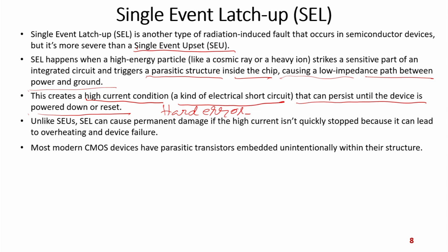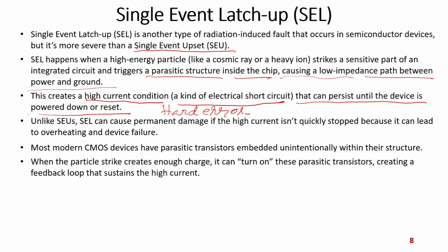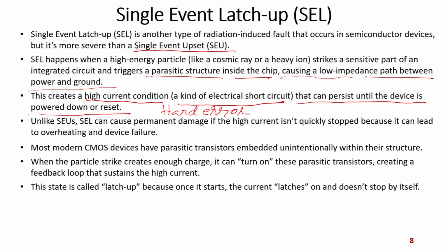Because of that construction of the CMOS device, there are parasitic transistors embedded unintentionally within their structure, and when the particle strikes, it creates enough charge to turn on these parasitic transistors. It can forward bias the parasitic transistors, creating a feedback loop that sustains very high current, and this state is called latch-up. Latch-up means there is a high current,